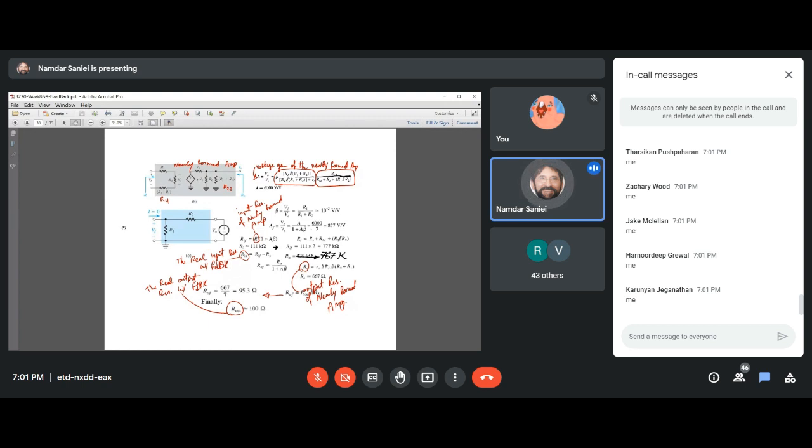Aniket, you probably missed this lecture, and in this lecture, we were talking about series shunt. After we calculated the output resistance, which was in shunt position, following the ideal situation, what we learned was that you divide the output resistance of the amplifier by 1 plus A beta to get the output resistance of the feedback circuit or network.